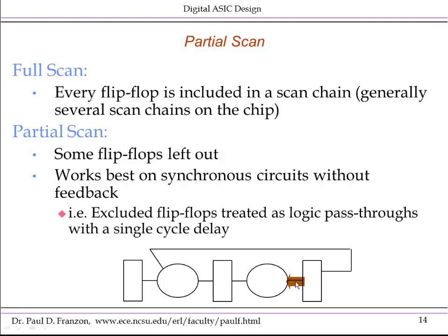This is called partial scan and it's fairly common. The complexity is that some of your logic has to be operated in this 2 clock cycle pulse rather than 1 clock cycle pulse. So it complicates the test sequencing of how you get things done. You would do this in separate test sequences. But it can be done. What it does, it reduces the overhead of having all your flip-flops being scannable. So these flip-flops are not scannable. Often in addition, there's methods to eliminate scan from the flip-flops in the register files and other large blocks like that, which I won't go through.